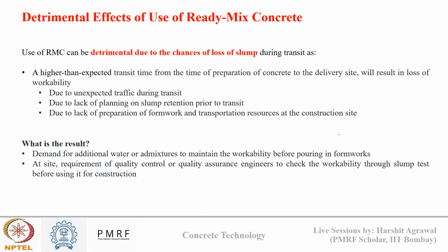However, at the same time, the use of RMC can be detrimental also. Why? Due to chances of loss in slump during transit. Suppose we have a higher than expected transit time, for transfer of concrete from preparation site to delivery site. It will result in a loss of workability.